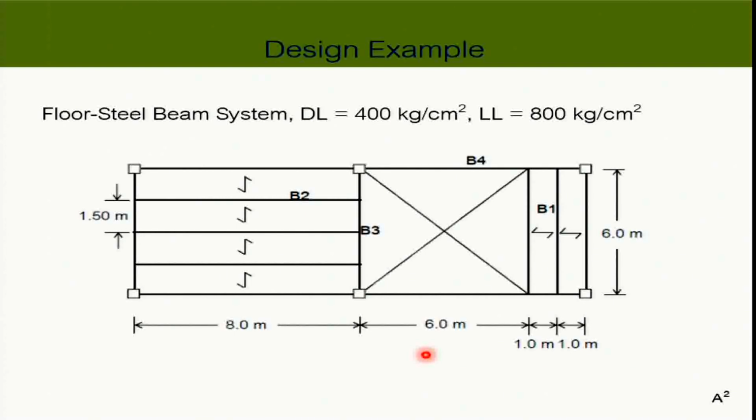And likewise, B1 as well, right? Because you have the concrete floor on the compression flange, and your beam cannot dance. The lateral torsional buckling will not occur in either B1 or B2 because of the automatic brace they receive from the concrete floor slab system.